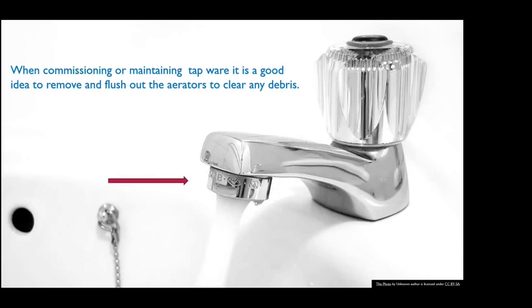which can affect the flow from it. Yeah, the bathrooms we were checking, I think we were doing exactly this today. He went through the bathrooms and we were wondering why the basin mixer wasn't really letting anything come out, and he took it off and all the copper shavings were there. Usually you can blow that out or flush it out by putting it upside down. But ideally, the best practice would be to flush it a little bit better at the pre-line stage, so you get most of it out, and then you might get a little bit extra stuff when you do the final fit off or something.